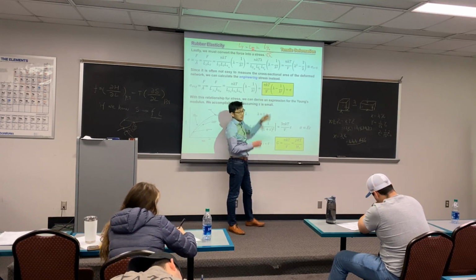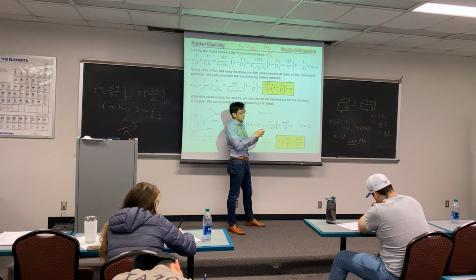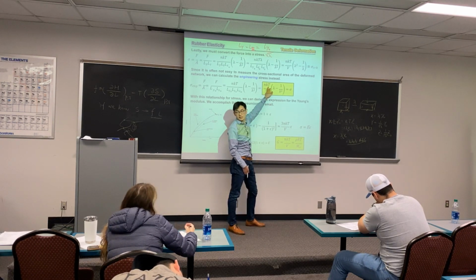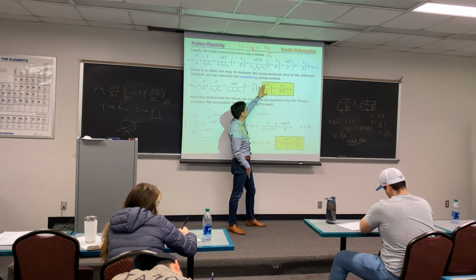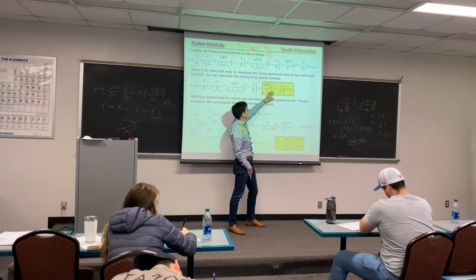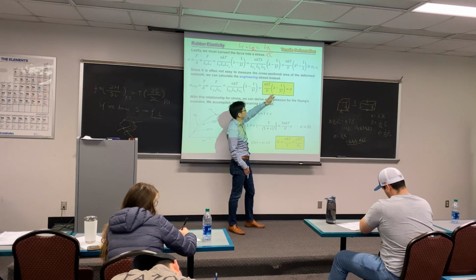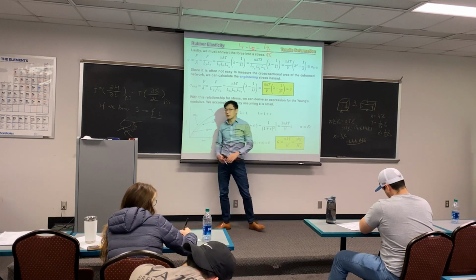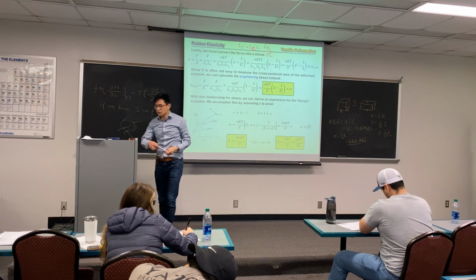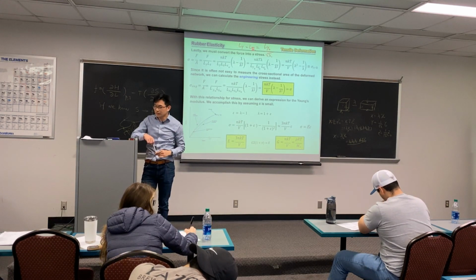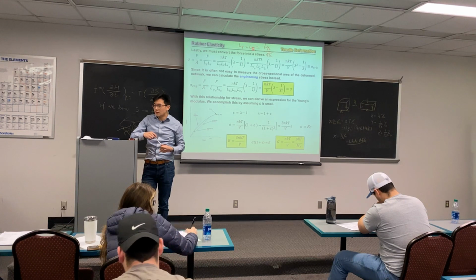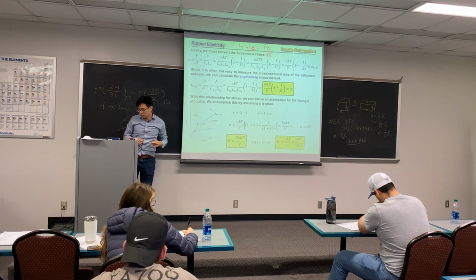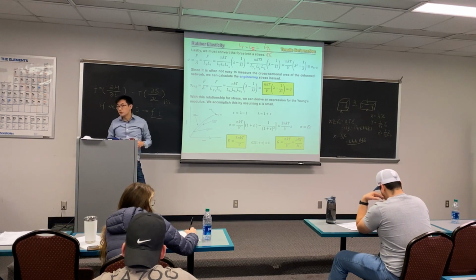The more strands in the volume means you have more crosslink points. K is a constant, T is constant at room temperature. So the number of strands relates to how much they deform. That's how you can predict the modulus of your rubber string using very simple entropy theory as well as the deformation.